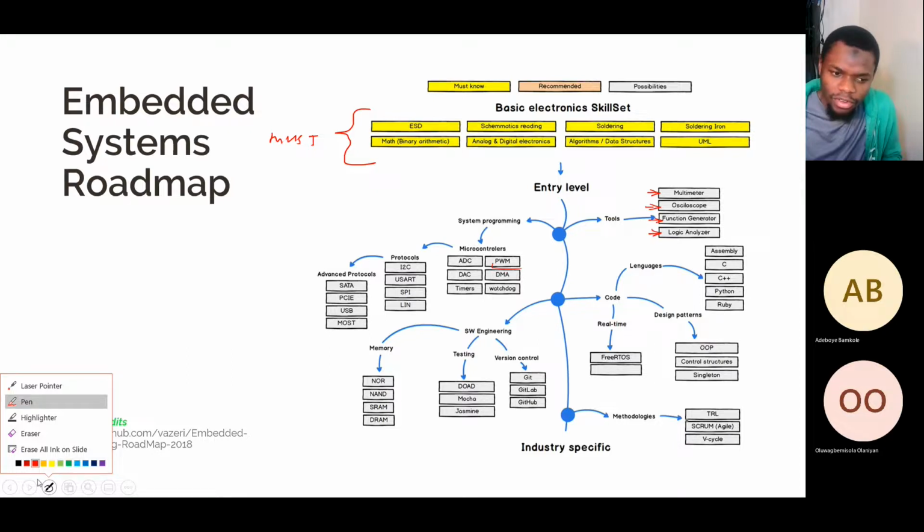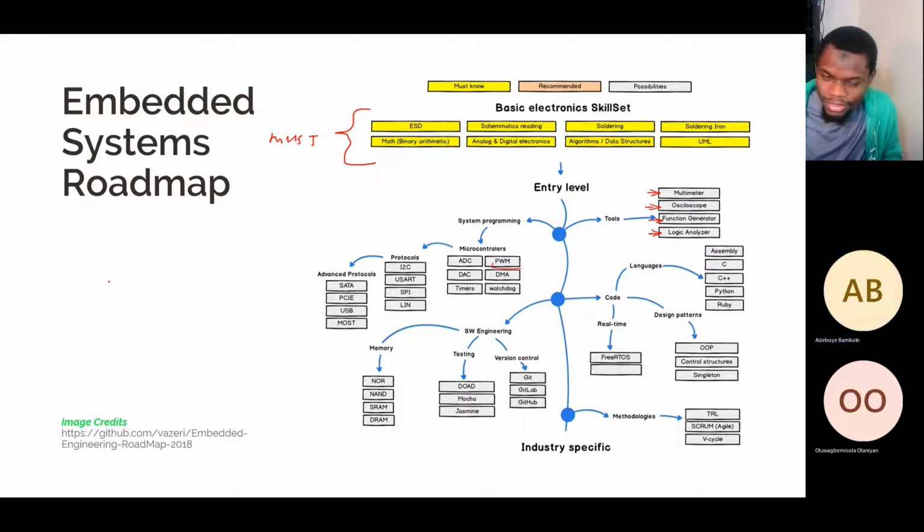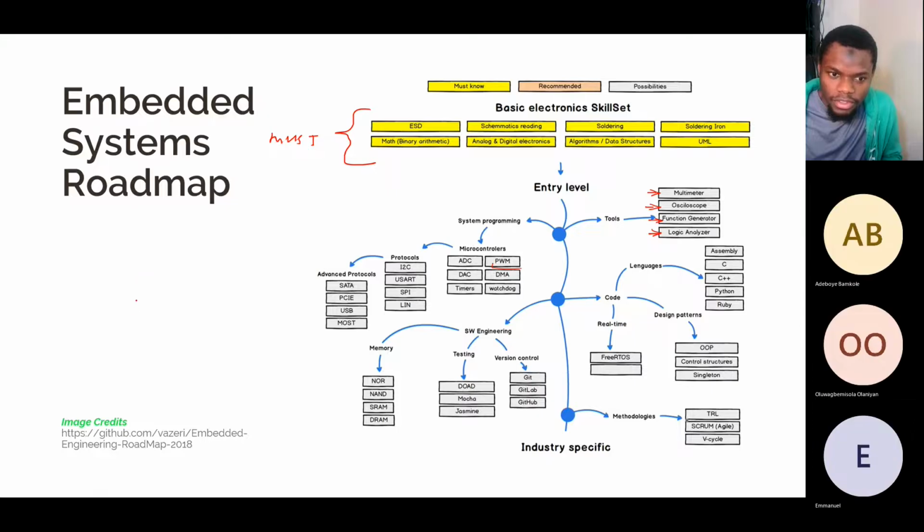Can we really call it analog? Maybe not, I'm not sure. I think it's like a blend of analog and digital in a way. It's not really analog or digital. You have 0 volts, and then you have 5 volts, right? PWM allows you to go between 0 volts and 5 volts, but the variation is happening digitally.